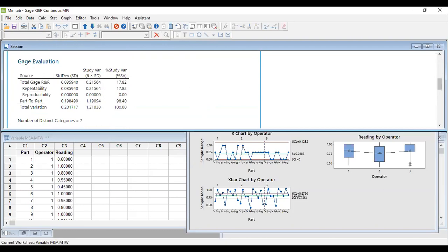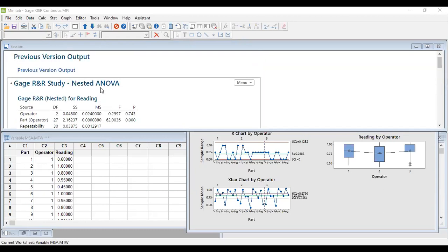Right now, there are 3 categories that we look at when we assess, in the industry standard, how to read this particular data. The first one, study of variation, right? If the study of variation is anywhere between 0 to 10%, the gauge is acceptable, right? Now let's see.